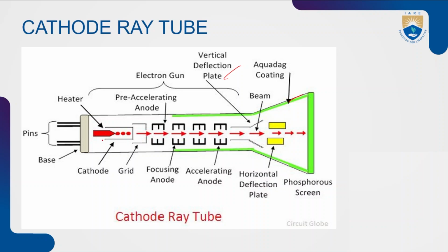As the electron beam comes from the electron gun, it spreads in different directions. As the beam spreads, its intensity reduces. So with the help of the control grid, we make all the electron beams coming from the electron gun focused in one particular direction. Like that, the electron beam is formed and focused in one particular direction.